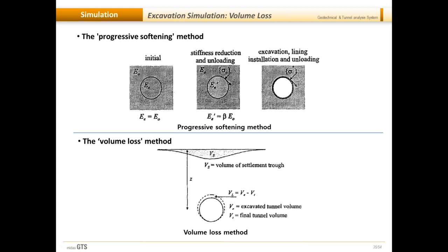But if you are working with finite element analysis, it is also worthwhile to perform a back analysis from this excavation to find out how much actual volume loss would have occurred. And depending upon the stiffness of the lining, even if, let's say, you have assumed 2% volume loss, depending upon your lining stiffness, you should activate the lining stiffness assuming the volume loss would be lesser than what is predicted. So you should activate the lining increments at, let's say, 1.5% of the volume loss, because under the given loads, the lining will also deform and the volume loss would further occur. So if you activate the lining after 2% losses, then the lining will further deform and the losses would actually be greater than what you anticipate. So in order to get the final profile right, assume a little less than the actual volume loss depending upon your lining stiffness.